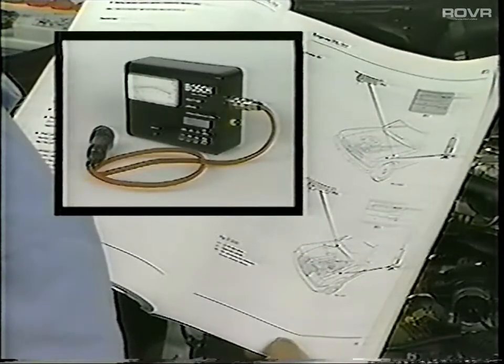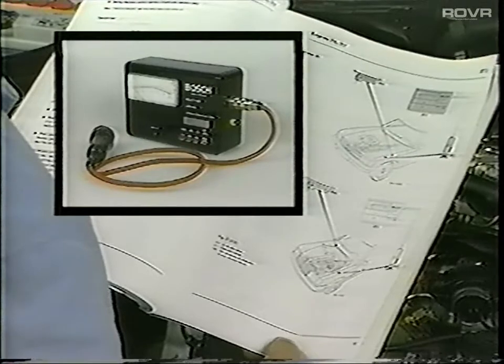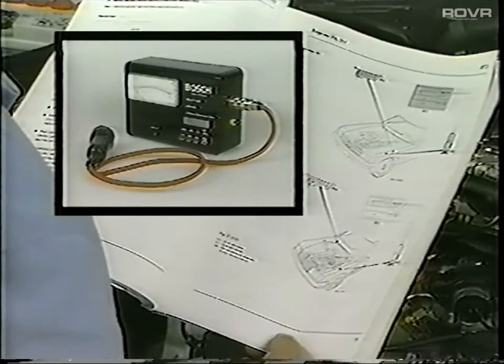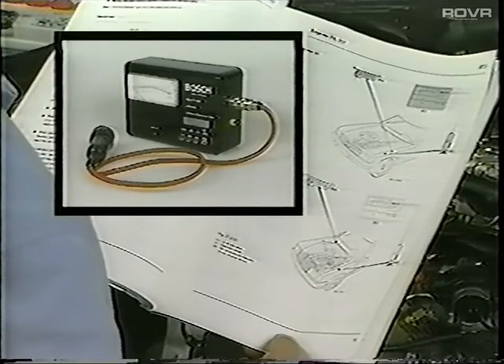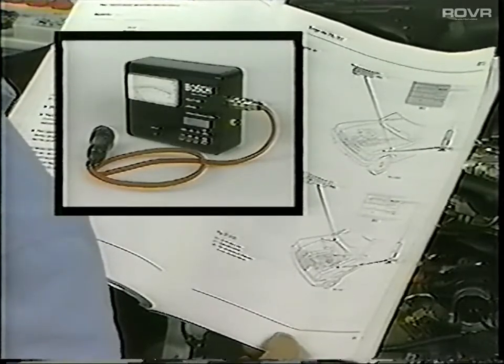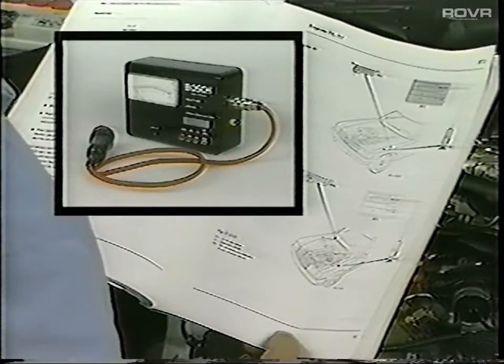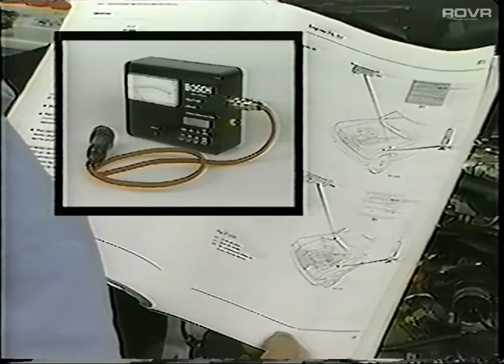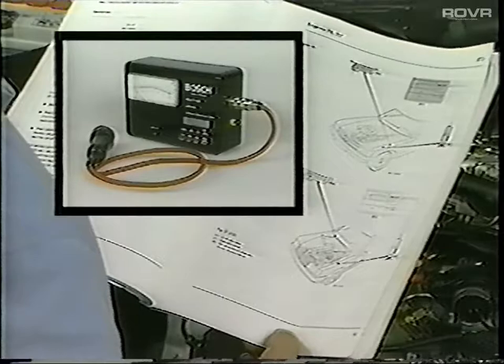An important change also related to all V8 engines is the adoption of the same procedure for measuring the lambda on-off ratio as used for the 6-cylinder engines. The idle ratio and ratio at 2,500 RPM are compared and must be within plus or minus 10. A detailed explanation is included in the introduction manual.